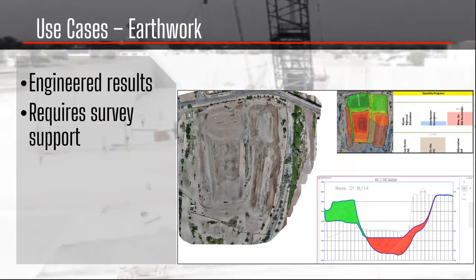And this is important for a lot of aspects, to know where we're going to be actually placing the building, like Eric said, checking for banks and making sure that everything is in the appropriate location, but also checking for water runoff, right? We're checking elevations and making sure that when it rains, the water is going to run off to the appropriate place and not pool up somewhere on site.